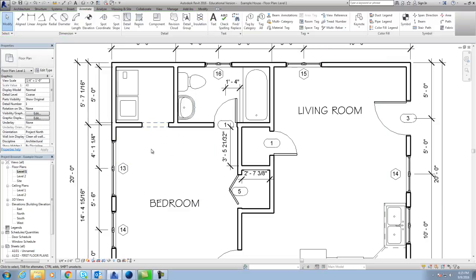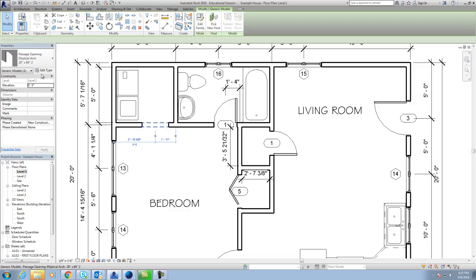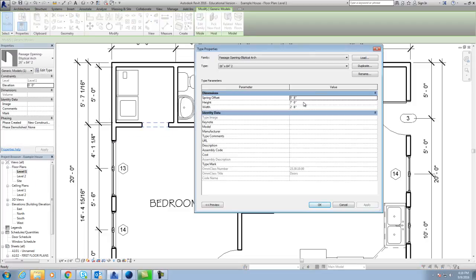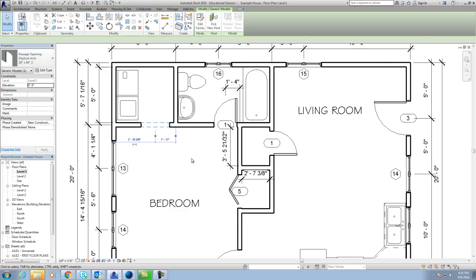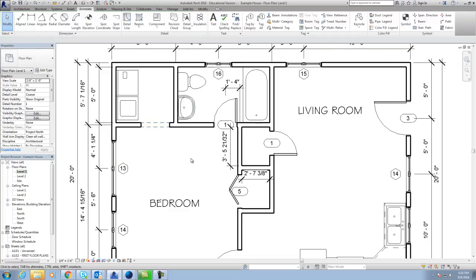Gives you a little bit more room. To be honest with you, every wall opening or door should be 32 inches, 2'8". That gives everybody an opportunity to get through, and it helps you to be able to move furniture around, but also it's accessible to someone that might be in a wheelchair or needs some type of assistance. They can get through these doors.